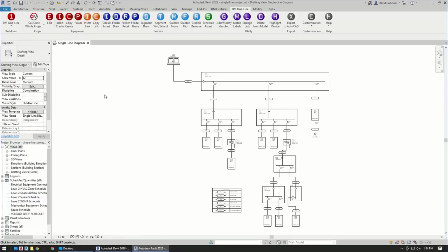It also means if you're bringing stuff in and you created your stuff at a different scale factor, you're going to have to redraw your stuff at the different scale. Revit has some scaling commands. It's hit and miss as to how well they work because Revit doesn't really like the idea of scaling things. So you might be able to rescale your stuff to match ours or rescale ours to match yours. You also might have to redraw some of it depending on how it's put together.